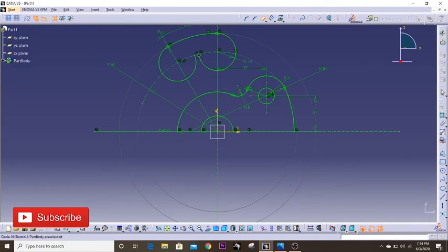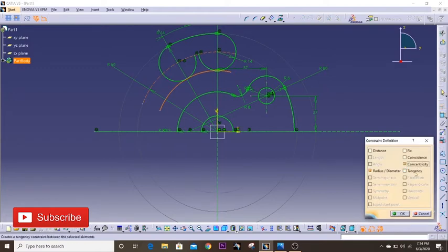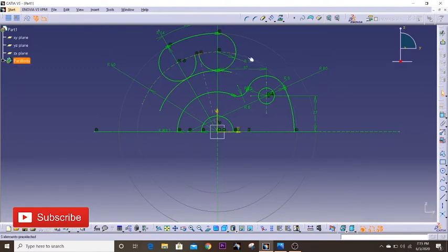Okay, so the same thing is going to go here. So I'm going to select the offset tool, and I come here. I'll remove this constraint. I'll make this and this concentric because obviously they have one common center of the arc. I'll make this and this tangential, and I'll just remove this constraint. Control Z. I'll remove this constraint. Perfect.